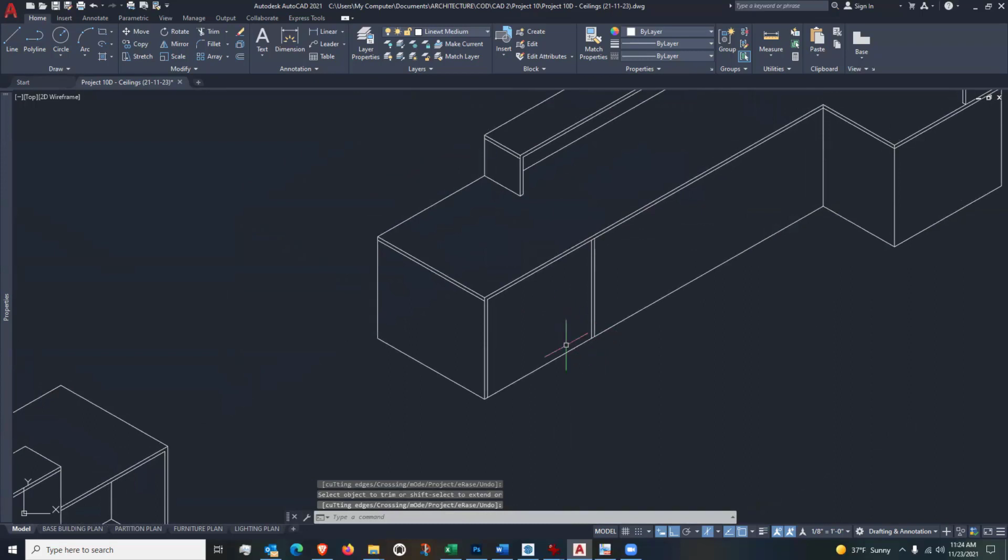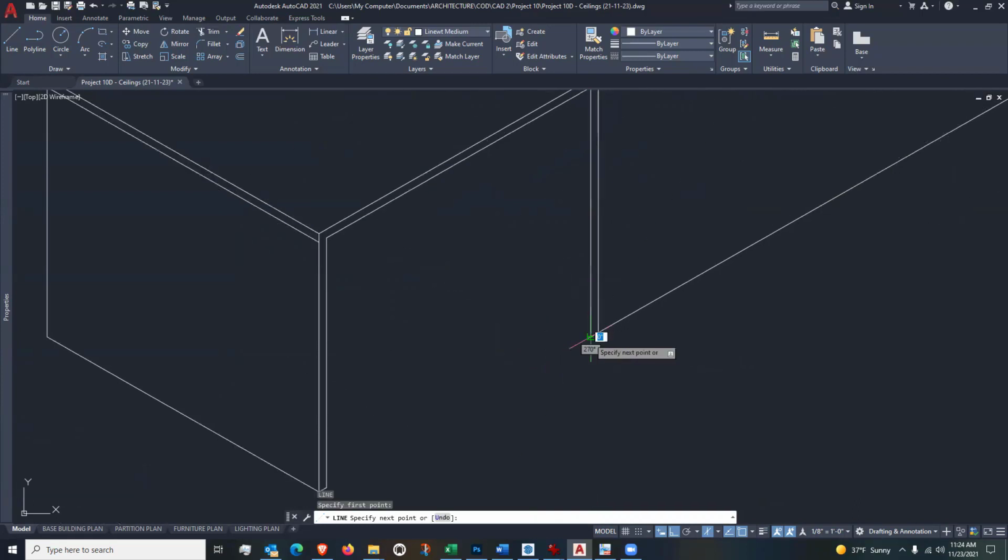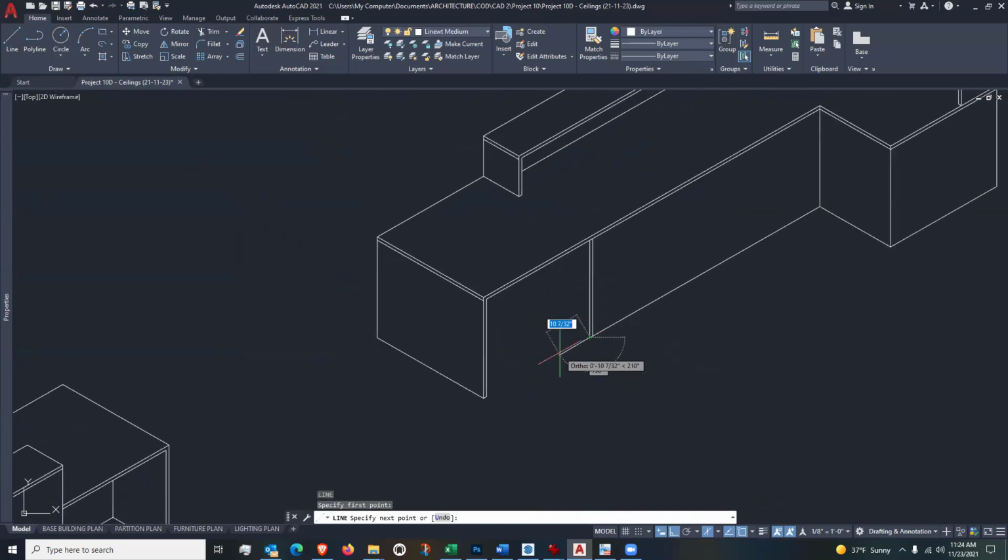And then I want to trim this. I need to draw the side of this panel here. So I'll just go with my line tool from here. And of course, it's not going in the direction I want. So I'll just tap F5 until I can. And then I'm just going to do the extend. I'm going to trim, hold my shift key and extend out.